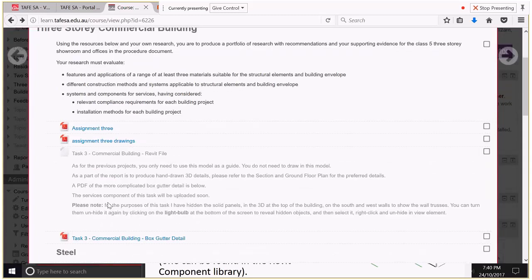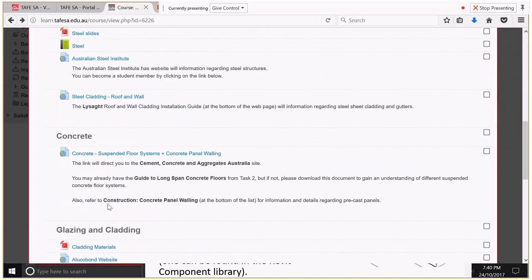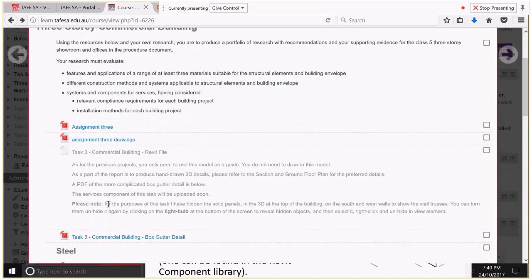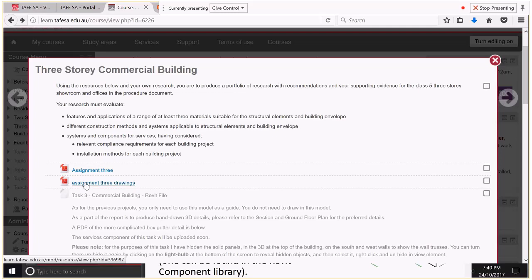Hence you have to do it manually, but you can also just draw. I don't know how you do it in Revit, but if this was in AutoCAD, I'd get the assignment 3 drawings, grab that roof plan, put it in as a PDF underlay, scale it up to the right size, and trace around the inside of the parapet wall. There we go. Then I'd create a little block that's 750 by 1500, and muck around with that. It'll take me 2 or 3 minutes, and possibly it's the same process in Revit.